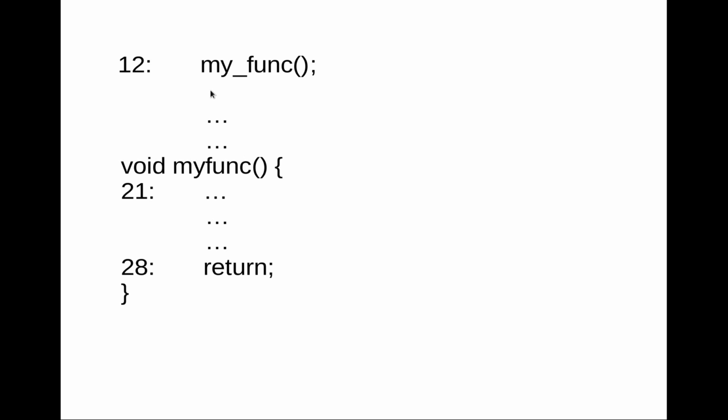And so the main idea here is that when we jump to this other location where my function is located, here let's say hypothetically that it starts at address 21, we want to first save whatever address we have here. So ideally that would be, if this were 1 byte, 13, or if it's several bytes, whatever the next instruction is after this executes, we want to save that address on the stack, so that we can then happily go about jumping into this function.